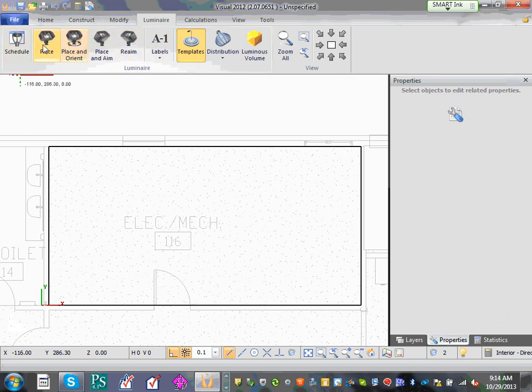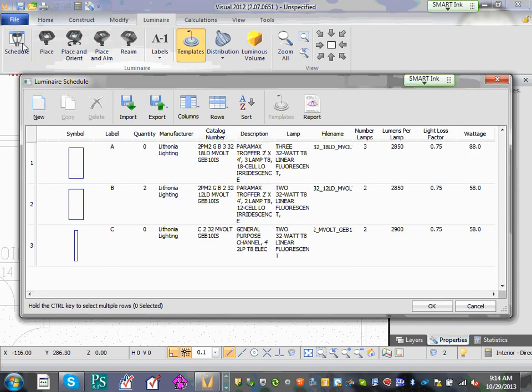So what if I just inject one thing and even leave it? If you do this, day one, when you run your project, if you did the 0.75, your project will be close to 25% brighter than what it should be. Be aware of that one, because the inspector might catch you on that. The day one calculation is based on 1% and 0.75, that's like 3 years, roughly somewhere in there.